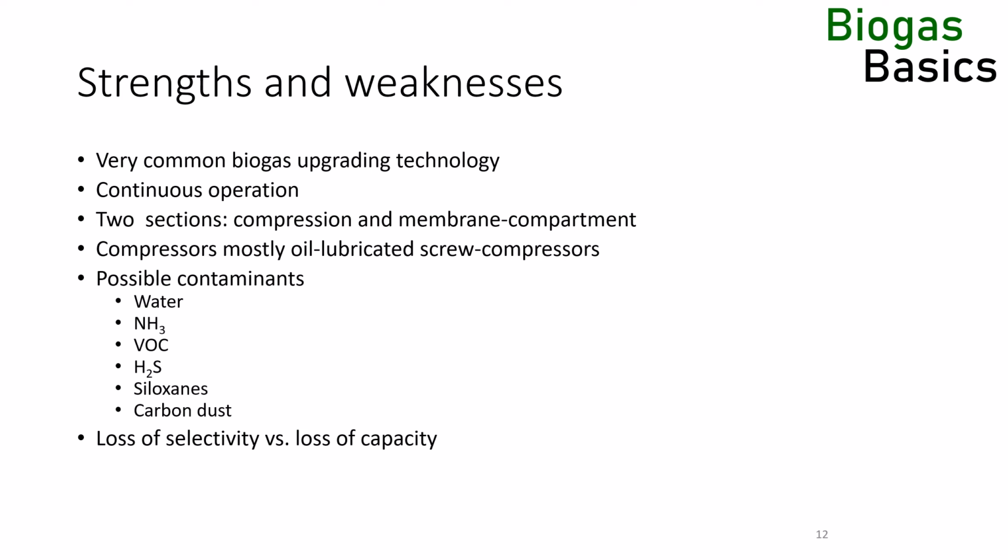A loss of selectivity happens when the membrane breaks and gas flows indiscriminately from the high to the low pressure side. Water contaminations are typical causes for a loss of selectivity. A loss of selectivity will lead to a substantial change in the pressures in the system. If membrane modules can be valved off individually, shutting off a membrane which experienced a loss of selectivity will lead to an instantaneous change of the pressures in the system.